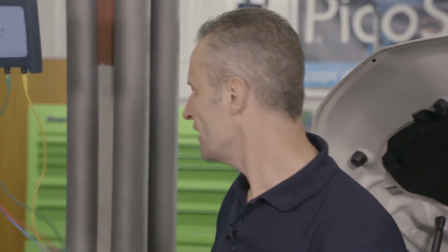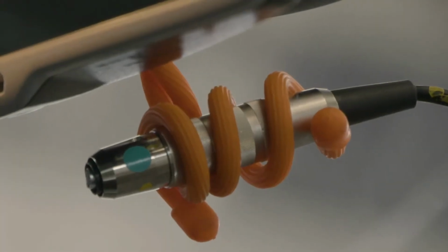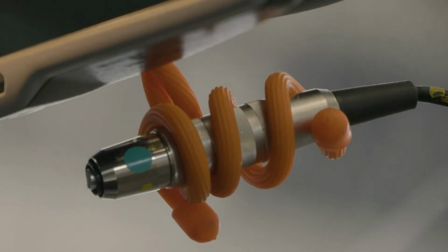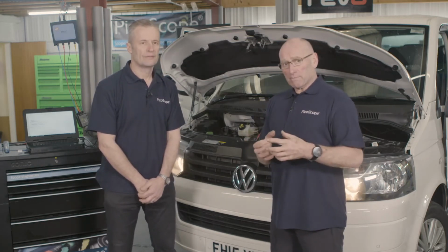So connection-wise, we've gone for 3-axis plus single channel. So still use one accelerometer measuring all 3 axes. But the additional channel, channel D, is the microphone connected to the rear view mirror. So in a road test example, the microphone will detect all noises, but there's a specific noise we're chasing here, which is the noise generated from the imbalance in the cooling fan. And I guess from this setup, would you also recommend moving the position of the microphone once you're honing in on the noise to perhaps increase the amplitude of the results?